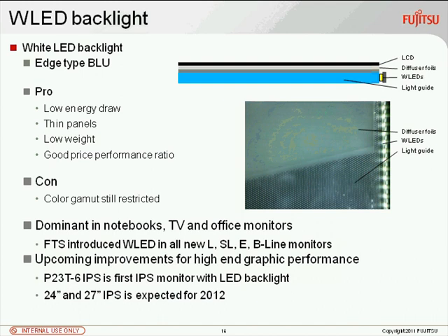The dots are smaller the closer they are to the LEDs, and bigger the farther away they are, because the LED is only on one side, and higher intensity is here, smaller dots let out the same quantity of light as bigger dots with lower intensity on this side. So the dimension of the dots makes the homogeneous light on the screen. But you don't want to see dots. That's why diffuser foils are used. In this display there are 3 diffuser foils, and these foils let you not see the dots, but make a very homogeneous surface on the screen.